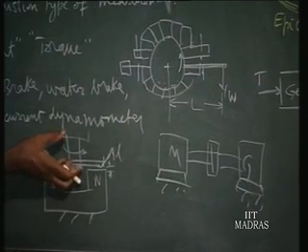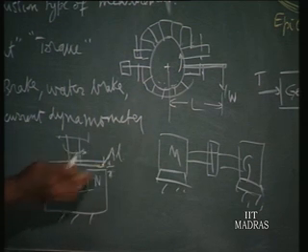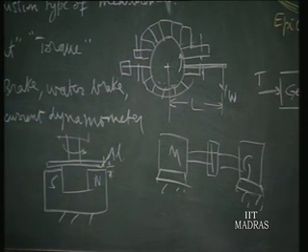Here also it is heated up a little, and the heat is dissipated to the atmosphere. So by changing the gap, we can have different torques on it, and the whole torque is absorbed. By measuring the gap, we can measure the torque applied on it. From some other calibration methods we can do it.